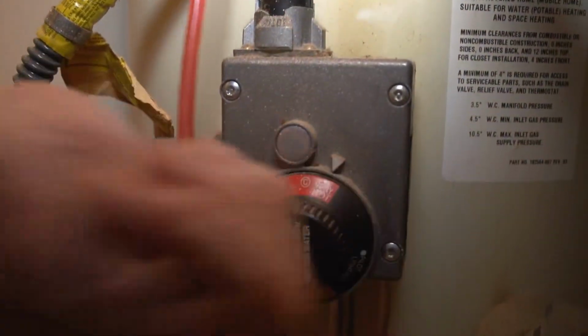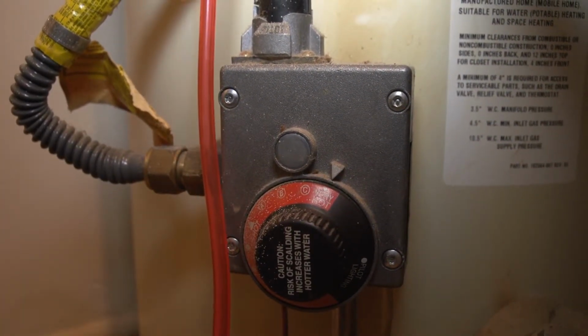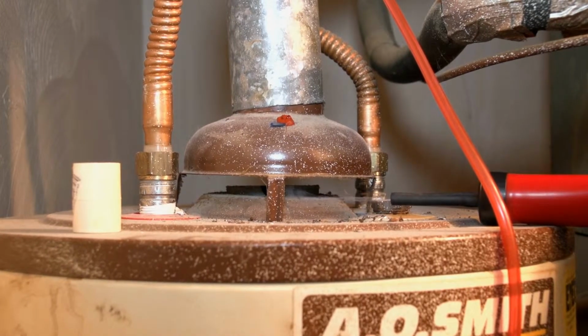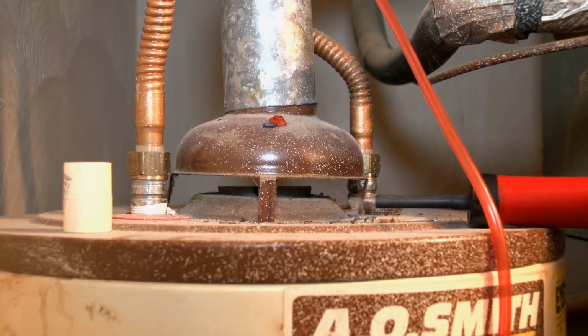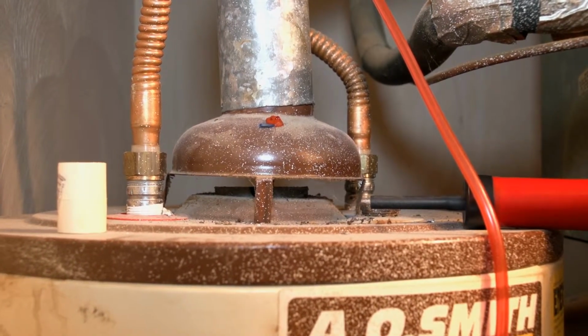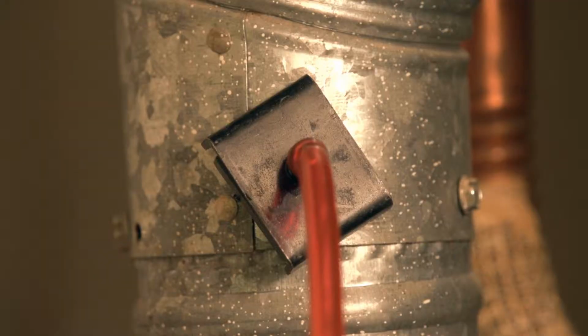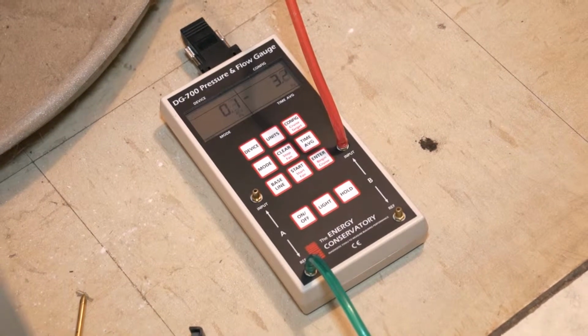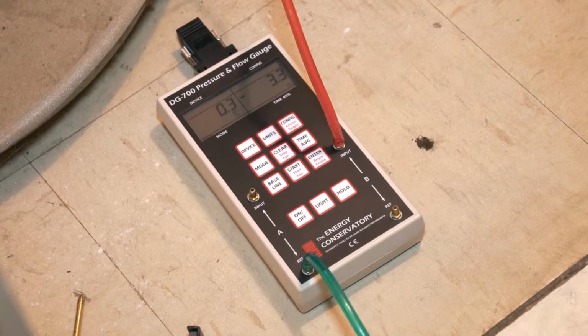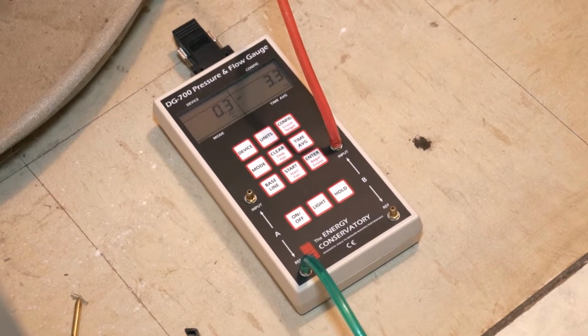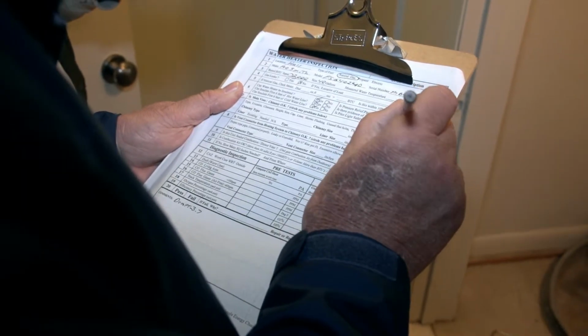So we will go ahead and turn on our water heater and allow it to fire up, at which point we'll use a smoke stick to test for spillage and make sure that we're not having combustion gases escaping into the house. After a set period of time, we'll go ahead and put our draft gauge into the chimney and check to see if the chimney is properly drafting. If it continues to draft well under worst case scenario, then once we've documented that, we can turn it off and go ahead and begin our test on our second appliance. In this case, it's going to be a furnace.